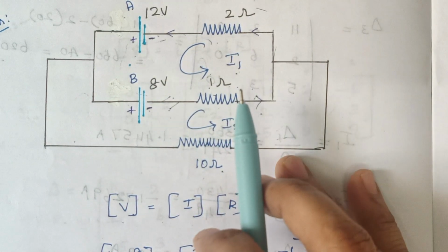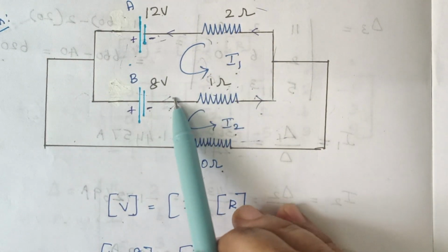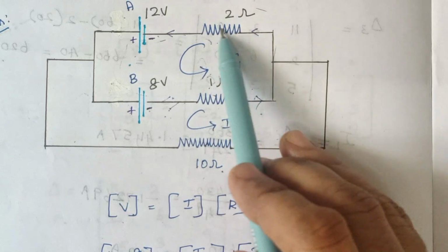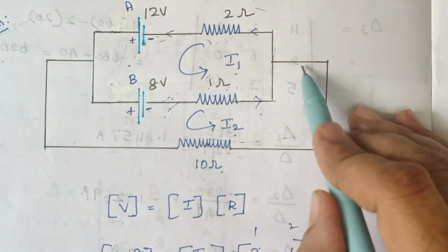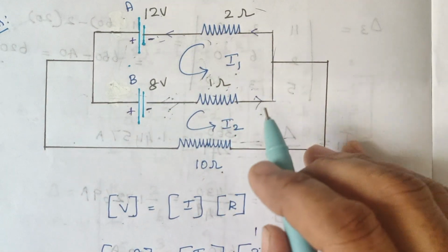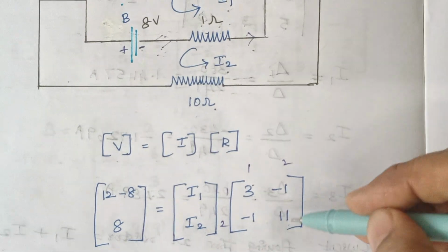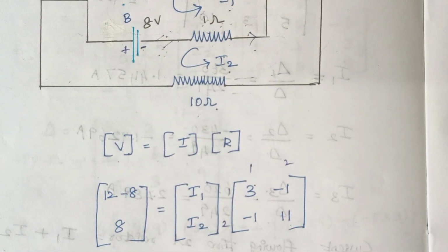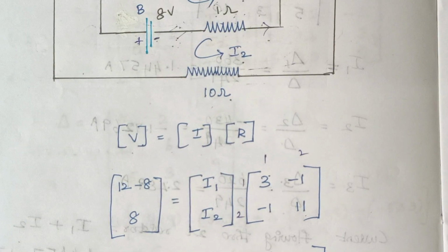Right. So, again now consider the direction. So, I1 flows through this 1 ohm like this, right? Because you see it flows like this in this way. Whereas I2 flows in the opposite direction. So, in this case, we have to include a minus sign, right? Therefore, minus 1 and minus 1 here. Am I making sense here? And this is the first step which has to be done by you perfectly. Once it is done, then the entire problem is over.